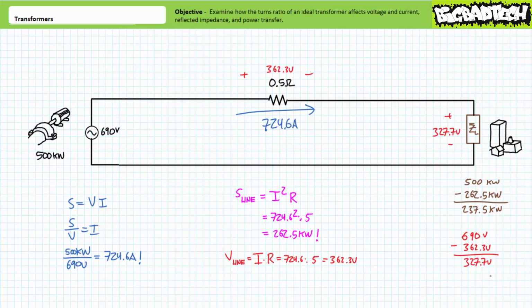This transmission scheme without transformation is essentially wasting more than half the power generated just getting it to the point of use. Rather than serving to transmit power, we've effectively turned the transmission line into a 200-mile-long toaster. This will not work, and another means of transmitting power over long distances must be employed.